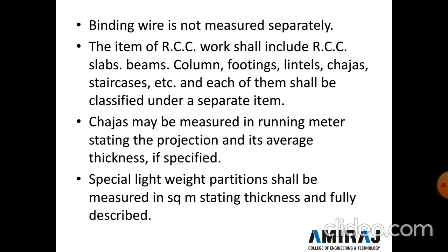Chhaja may be measured in running meters. Why may chhaja be measured in running meters? Because chhaja requires only a small thickness. If we provide a slant slope in a chhaja, we calculate the average thickness in running meters. Specially, lightweight partition walls shall be measured in square meters of area, as lightweight partition wall thickness is less.